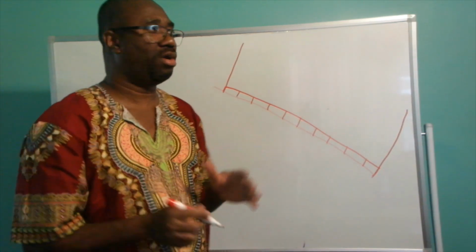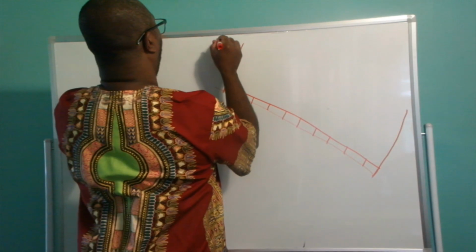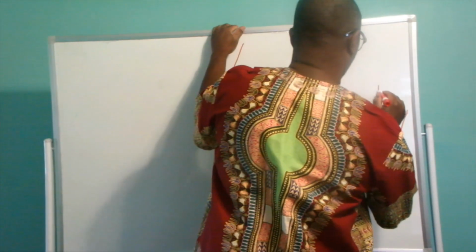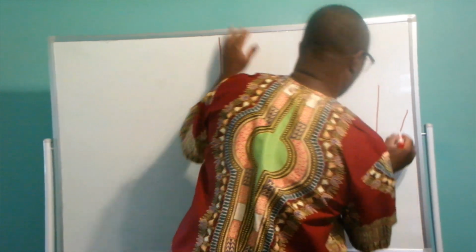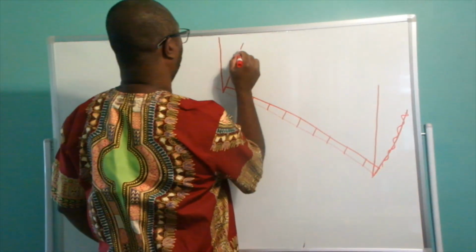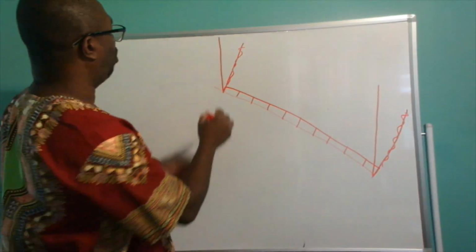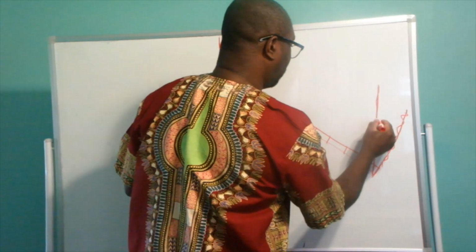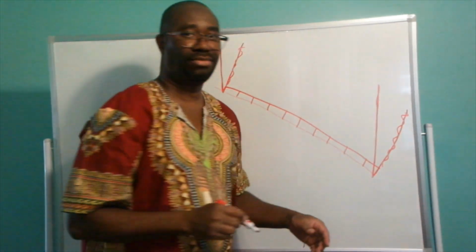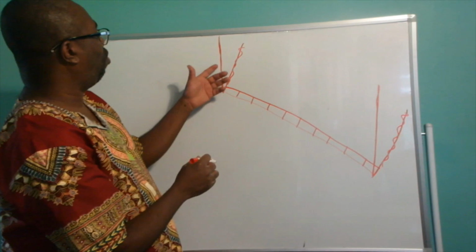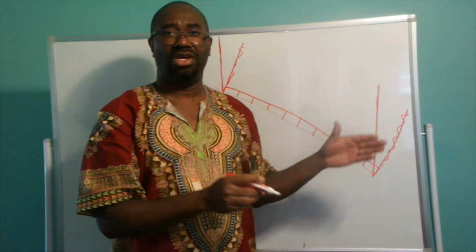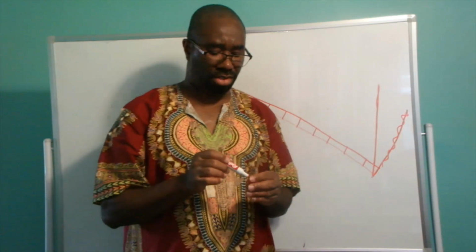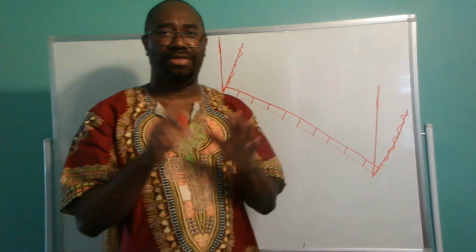So you would rather want your wall to go up vertical like this, right? So you want your wall to go up vertical like this on your slanted land. And in order to get your wall to go up vertical like this, you will have to step your foundation. So stay tuned and I'm going to show you how that is done.